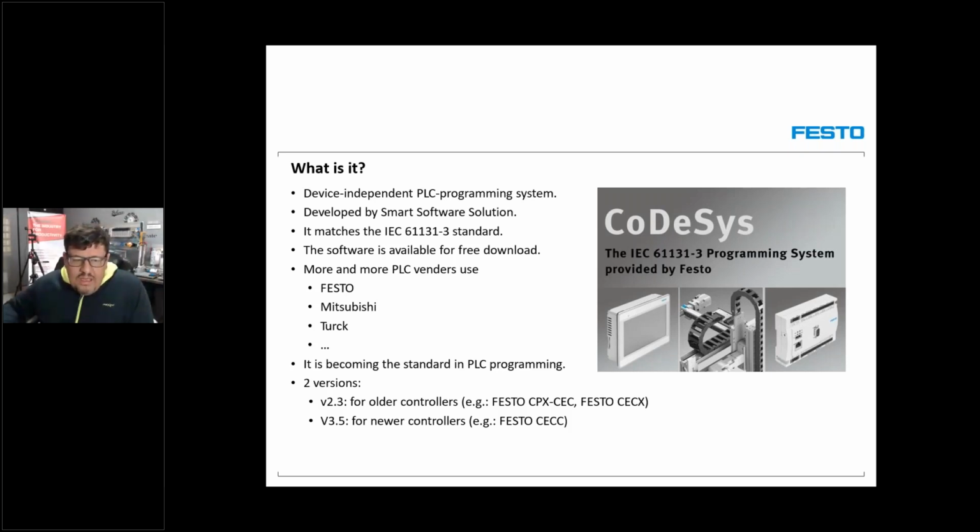More PLC vendors, that means companies that manufacture PLCs, are also integrated into the CoDeSys software, and you can utilize that software to program and configure your PLC. Festo is one of the companies that has its own CoDeSys software, the same as what the 3S Smart company from Germany developed. It is also a standard within PLC programming. All the PLC programming languages within CoDeSys are according to the IEC standard, and I'm going to explain that to you a little bit later on.